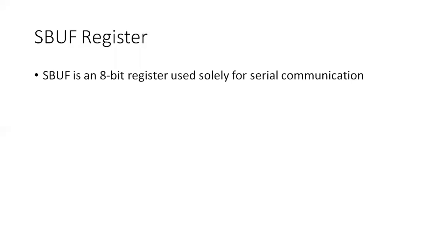SBUF register, this is very important. The SBUF register is nothing but the serial buffer register. What is meant by buffer? Just a storage, right? This serial buffer register is an 8-bit register. Whatever data you want to transmit, you should initially load into the SBUF register. That is the main purpose of the SBUF register. So the data you want to transmit should be loaded into the SBUF register, which is an 8-bit register.